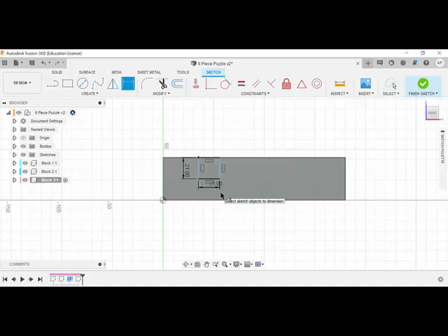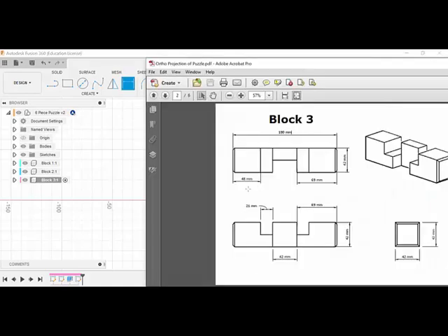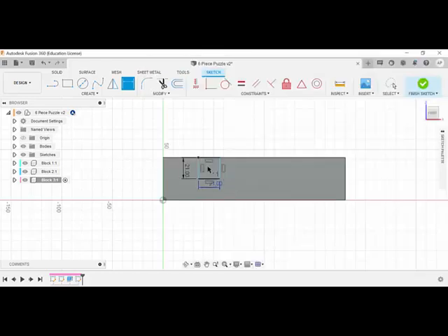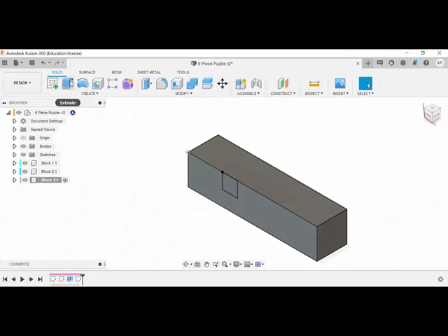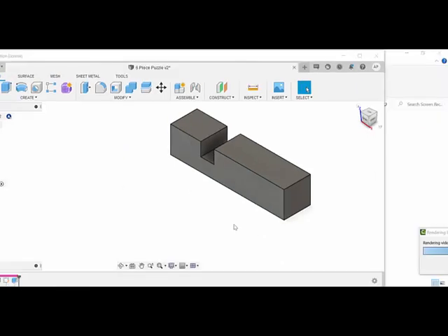by 21. And again, the reason why I said 48 is because the edge of that lines up and it's letting us know that is 48 millimeters across. There is something there to look at, which is the edge of that corner. So we're here, clicking on that, moving it up, calling that 48. We're then going to finish that sketch, get the extrude tool, and we're going to minus that 42.